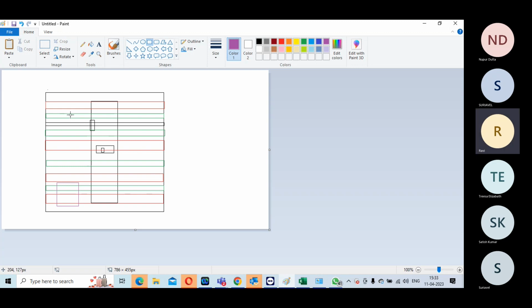This is a separate power domain. You understood? Only the power gator will have two domain connections, but the rest of it will be like this. All your M1 should connect only to this. In the methodology where I'm not adding any breaker cell, this particular always on cell will be double height without this M1 rail.